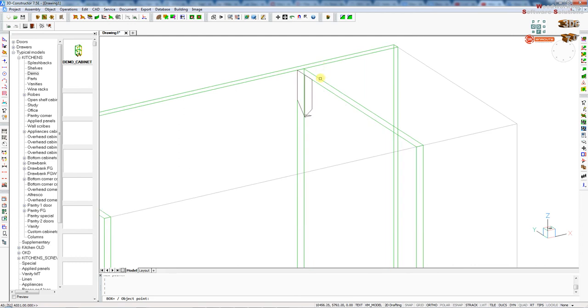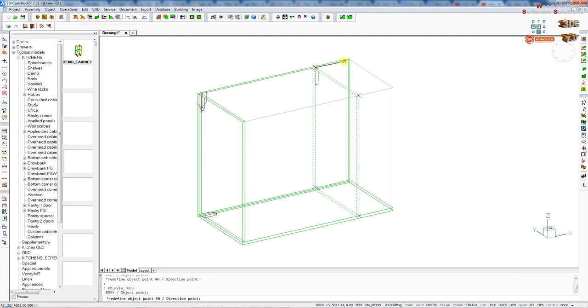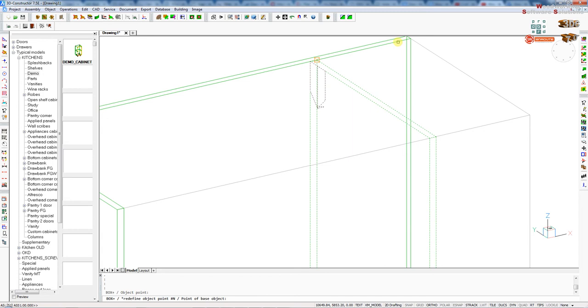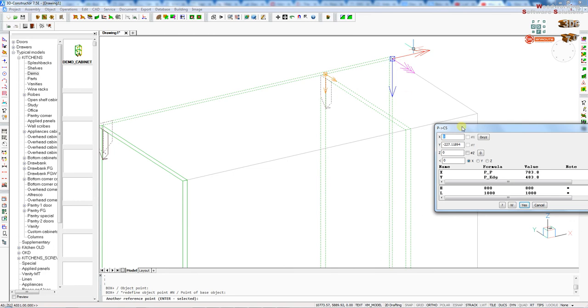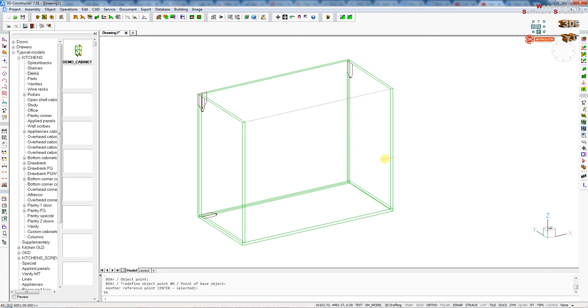So you will select a line, and our software will hook to, or reference to, the corner. We will select a second line of the back, and we'll select a line on the part. We'll select a line of the back. The software will specify the point on the back, and now we will press this button that will put all figures to 0, all x, y, z positions 0. We'll click yes, and now the part is sitting in position.